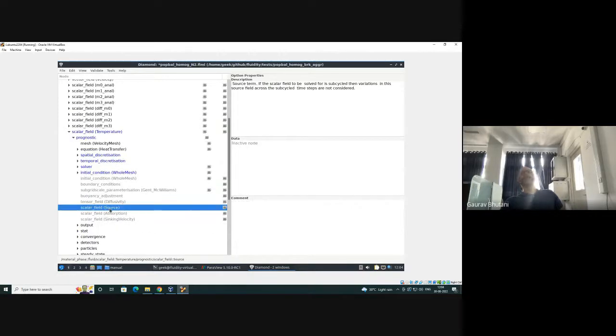So you can include a source term, if heat is getting generated because of some electrical heating in the system and so on. In fact, we have examples where heat transfer is also getting solved, so you can look at those examples. Ultimately, Navier-Stokes is slightly complicated because you're solving for velocity and pressure equations coupled to each other.